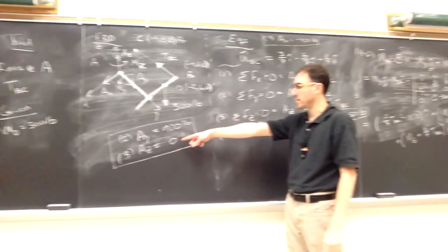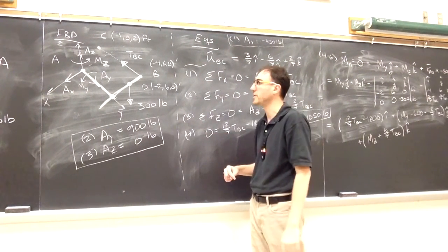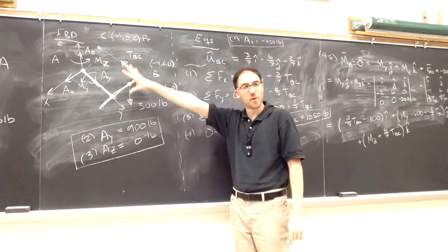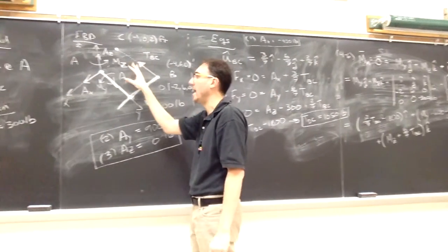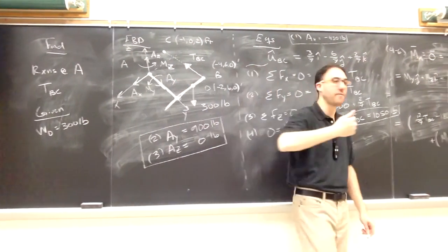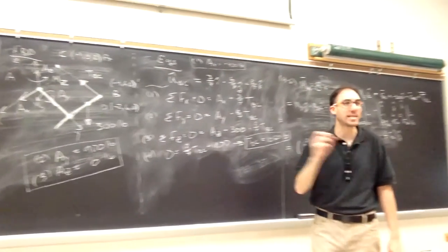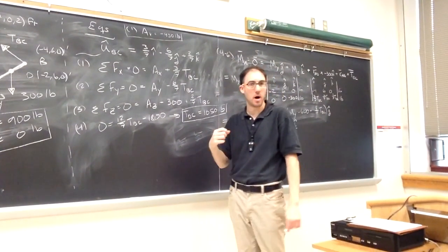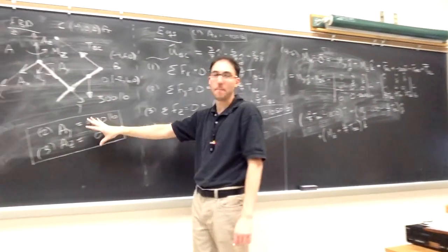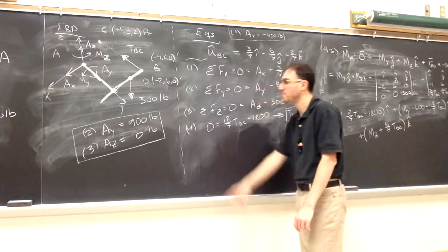It turns out that there is no force exerted along the Z direction on the pin. The free body diagram, though, doesn't know that. We're just drawing what it does prevent from happening. It doesn't mean that it needs to exert any force or any couple along that direction, but that's at the math step, we'll be able to determine that.